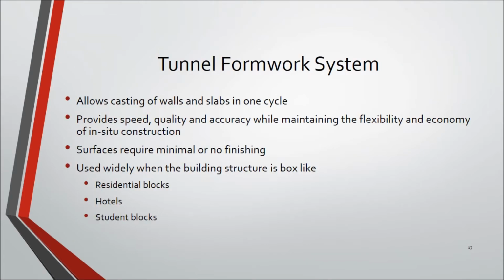Tunnel formwork systems are not literally used for casting in tunnels. These are used on high-rises for casting of walls and slabs in one cycle. The name tunnel form comes from the shape of the formwork system. These are used mainly for construction of residential blocks, hotels and student blocks. In the next slide you shall understand why these are called tunnel forms.